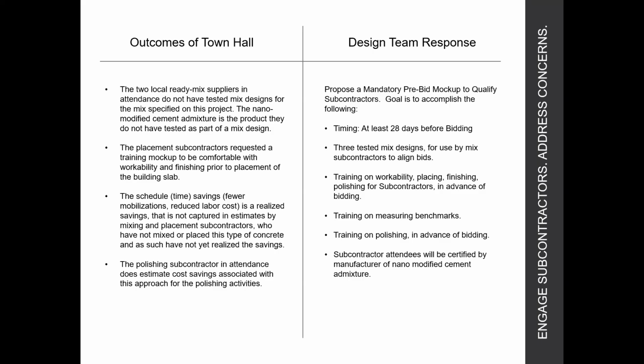Okay, but the goal was to have 3 tested mix designs. We decided we were going to do 3 slabs, 3 different mock-ups. Each mock-up was assigned a different local ready mix supplier. And that ready mix supplier was teamed with one of the admixture manufacturers. So each team was going to pour one mock-up and place and finish and all of this stuff.